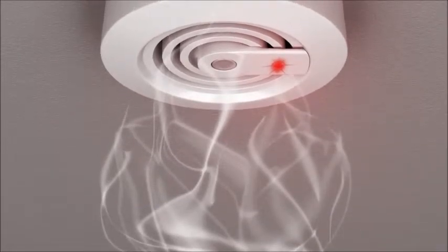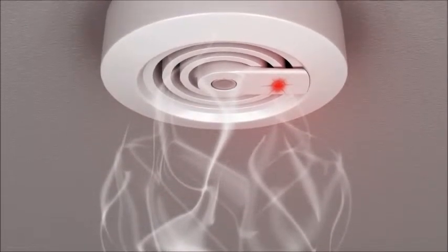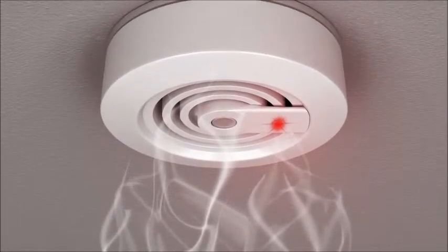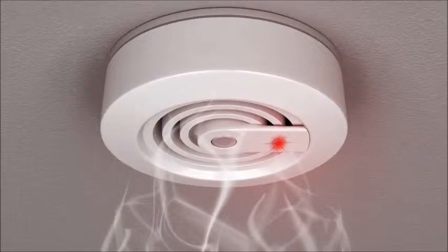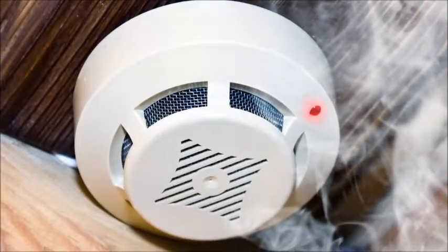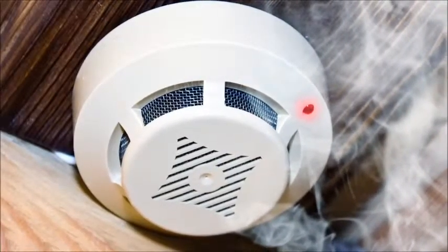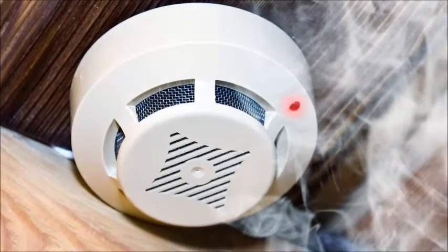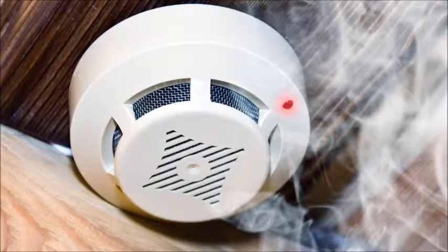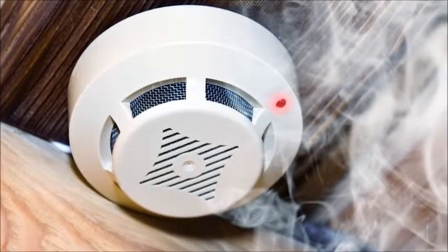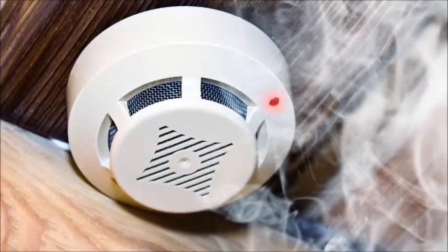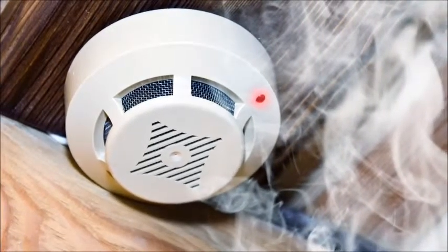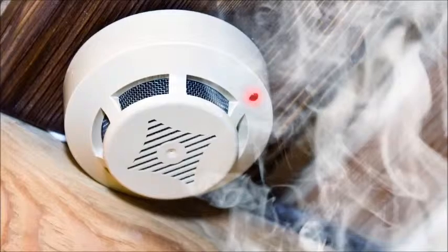What is actually happening in photoelectric fire alarms is the LED sends a beam of light, usually down a T-shaped chamber. Sitting at the bottom of the T is the photocell. When smoke enters the chamber, some of the light is scattered by the particles, with some rays getting sent down to the photocell. When this photocell detects light, it generates an electrical current that triggers the alarm at a certain threshold. Once that current stops, the smoke is cleared, the alarm will stop. Photoelectric detectors are better at detecting slow smoldering and therefore generally smokier fires.